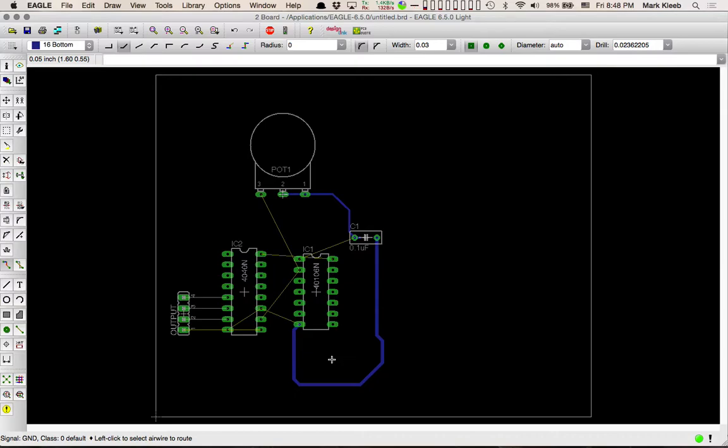If you overlay a trace, it's like not allowed. Right. Because this isn't like the schematic view. This is actually what the board is going to look like. So if you draw a trace over another trace, they're going to connect together. So that's why this part is sort of like a game, because you have to figure out how to connect all these lines without crossing them.